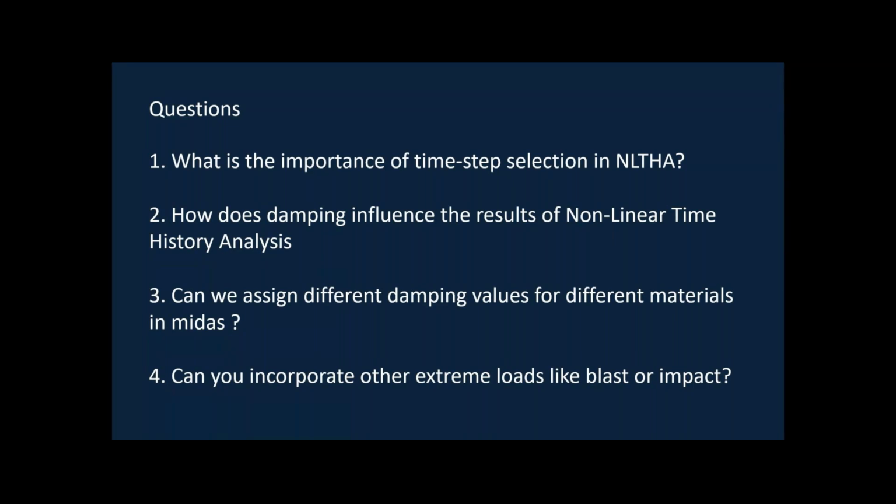Coming to the first question, what is the importance of time step selection in nonlinear time history analysis? Choosing the time step in nonlinear time history analysis basically depends upon the sensitivity of the time step. Generally, it is a rule of thumb that depending upon the time history records that we have, we know that when we generate time history records, they are spaced at one particular time interval. Let us say that it is around 0.01.